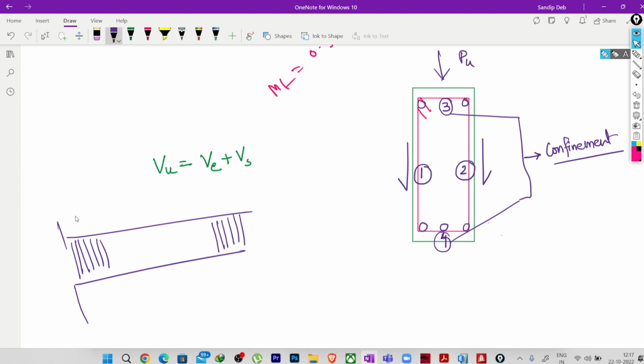The shear will be higher there, so to resist the shear we have these 2 legs, and as the shear is higher there is scope for the concrete to fall apart. To keep the concrete together is what confinement is. So the more you provide, the higher the confinement along with higher shear resistance. We will discuss that later.